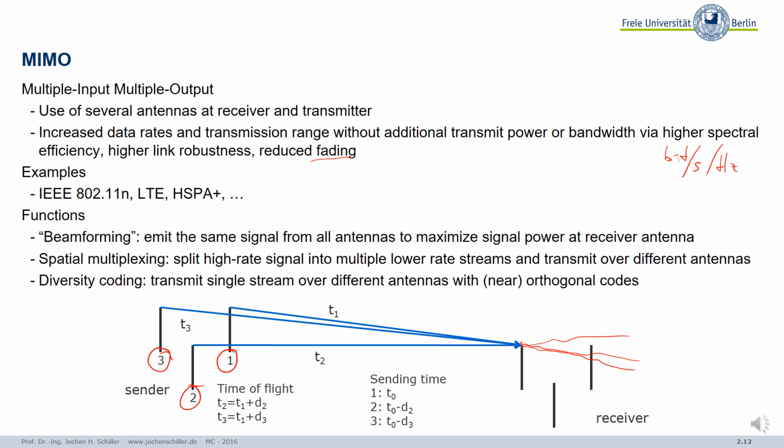You can also use MIMO, for example, that you say, okay, for my TV set, I assign this and that antennas, and for the mobile phone at home over wireless LAN, you assign another antenna, things like this. You can also do this kind of multiplexing, but beamforming is very fancy. So you can have good utilization of your space. Because otherwise, without beamforming, you have a problem. You can imagine you use the same frequency for all the users. Somehow you have to separate them. We will learn how we separate, but space division multiplexing is one technology. So quite interesting, this beamforming thing.